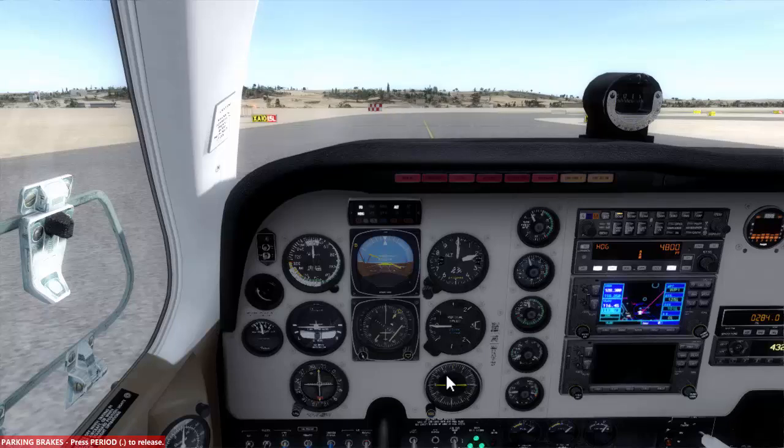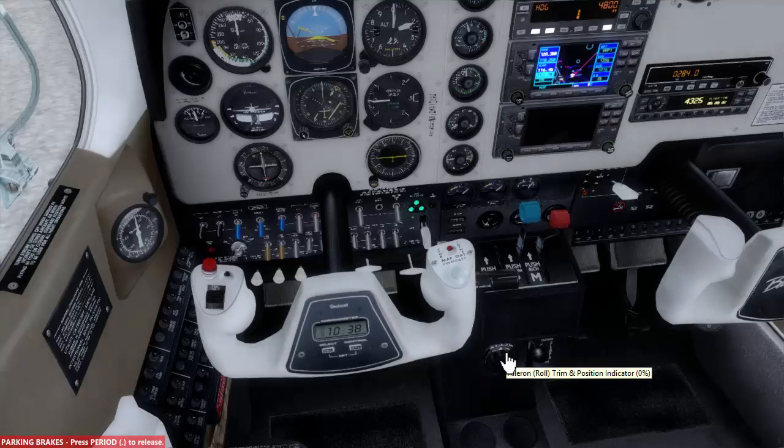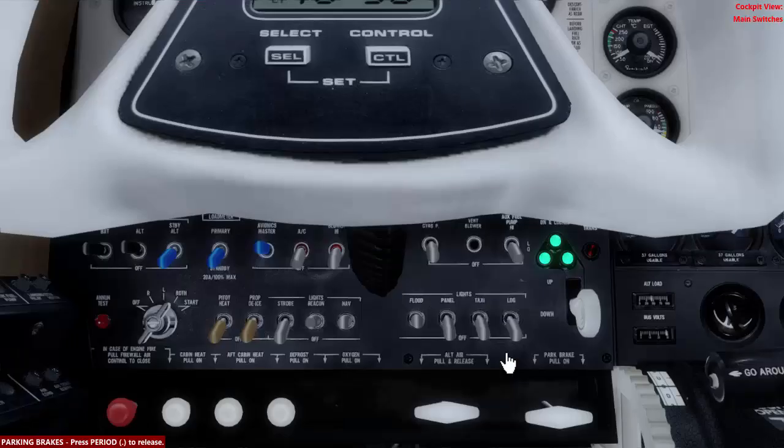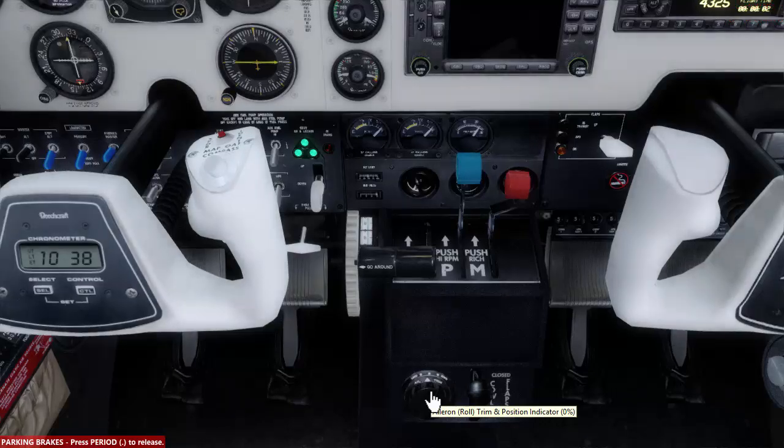And when taking off, I won't put this aircraft on the number in the runway because we need as much length as possible to take off. We don't want to have a problem in which we are running faster and we don't have enough length in the runway. So also the aileron trim must be neutral, that is to 0, and we need to have it in 0 position.